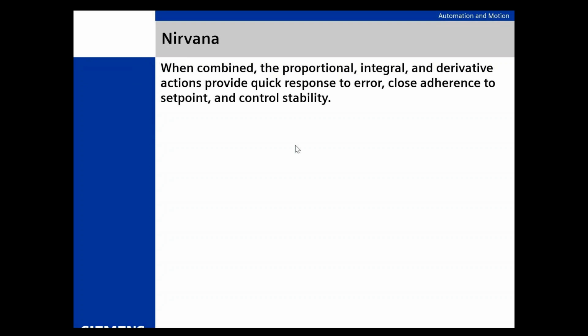That's not always the case. But like I said, you need to always know what PID is in any loop in case you trash your controller, in case somebody makes some changes. You just need to know that. Don't auto-tune. Do yourself a favor. Don't auto-tune and say, oh, great, it's working, and walk away. You're going to get bit with that. Know what the controller came up with. Anything else?